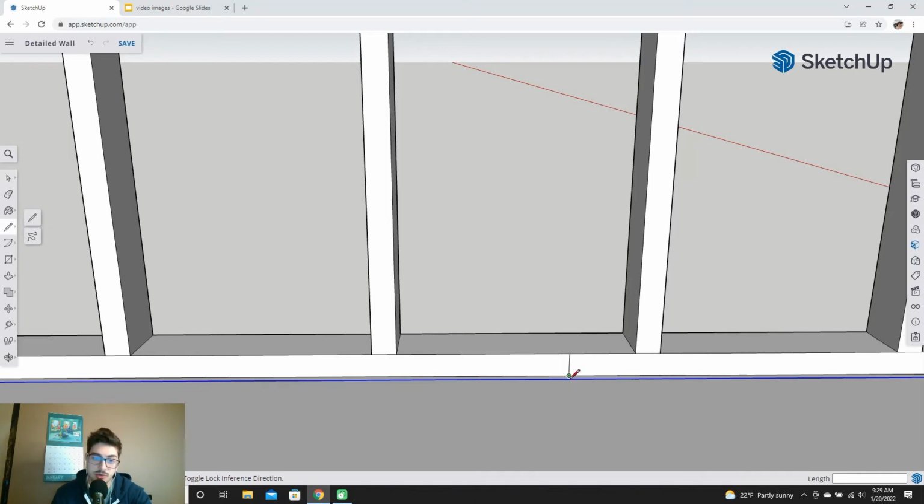Now, I said it was going to be a 32 by 80 door. Here's where having some knowledge of houses is important. When you do a rough opening, which means you're framing in a wall, you actually want to add 2 inches to both dimensions for your rough opening. So 32 by 80, you're actually going to make an opening with your 2x4s that is 34 by 82, so that you have space for the trim, like the door that gets hung on its hinges and then put in frames that stop it and have the little spot for the latch.